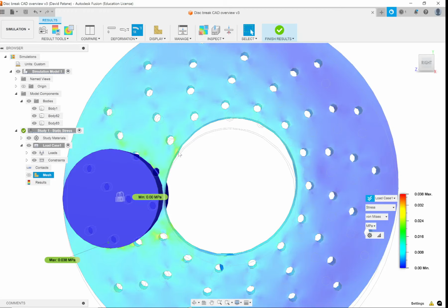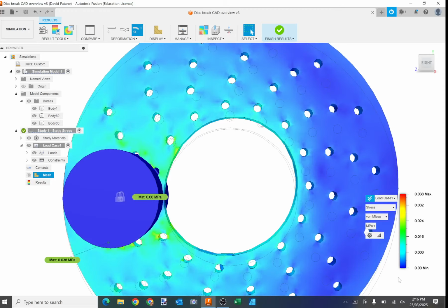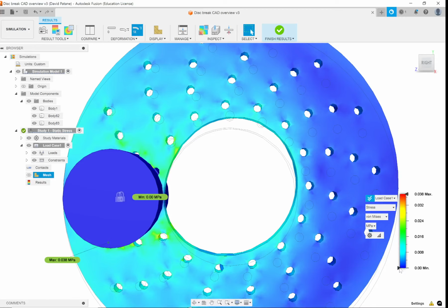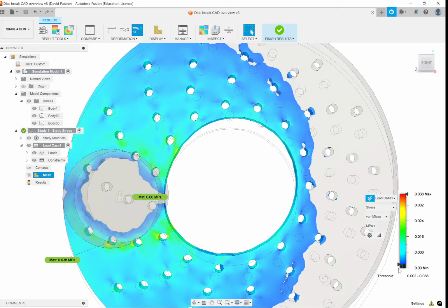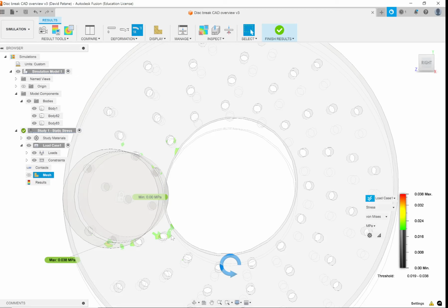I picked an arbitrary number of 100 newtons, but let's say you have a race car and, from that braking question we did here, we know how much we need the brakes to perform for our car to reach a certain performance. We divide it by 4 brakes, so we can then see how much our actual aluminium will deform. But then we can also see where it's the most red, where we can eliminate all this low pressure stuff. And we can say that where it's the most red is where it's most likely to crack. That's where the most stress is.